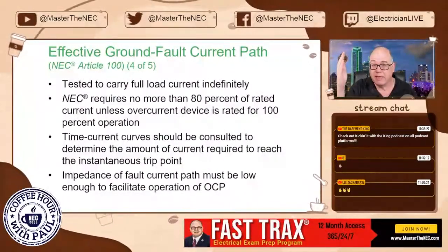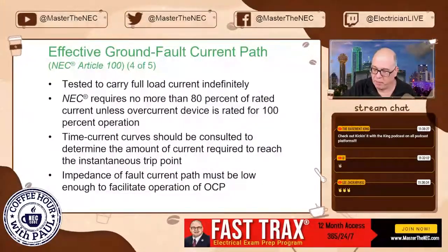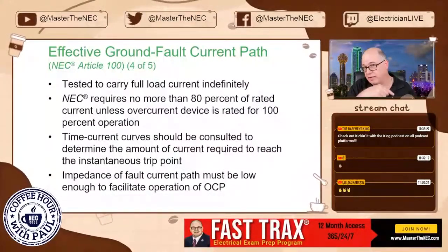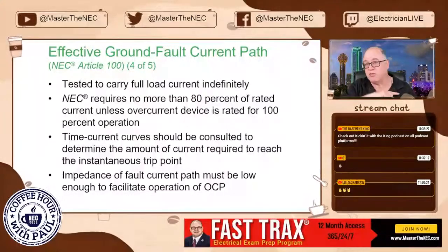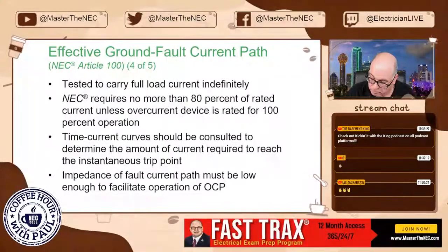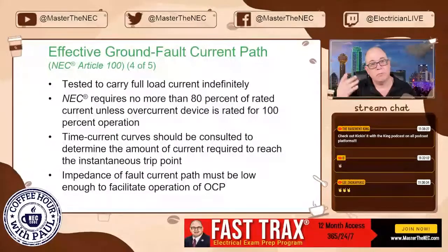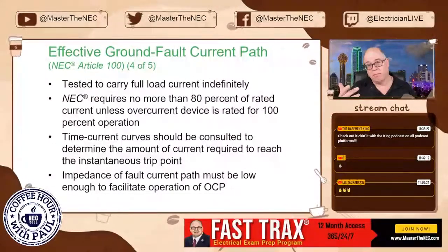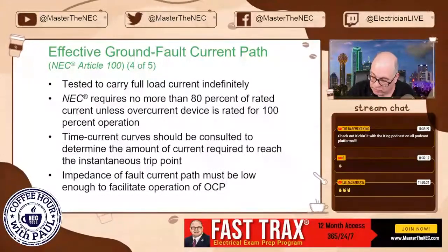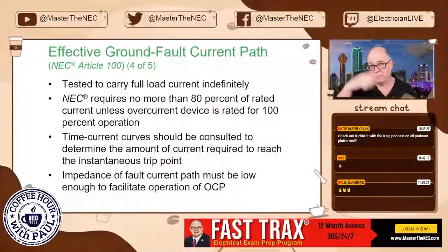If you've got the breaker, then you're going to do what? You get it. If it was a 20 amp overcurrent device, let's do the math. You want to find out what the current limit is of a conductor so that the continuous load is not going to exceed the rating of the device: 20 times 0.80 is 16 amps. If you want to check that, then you go 16 amps times 1.25, which is 20 amps. So multiplication either way to do it.